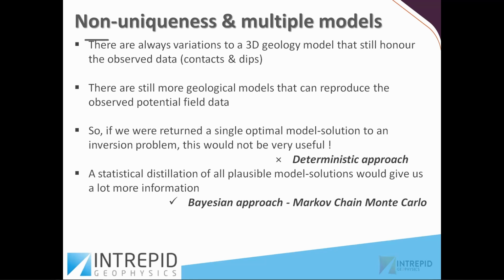So our job is to reduce the number of models that we are getting out of the inversion product. How can we do that? We can apply some additional geological information into the model to fix some of the layers, so that this layer should not change during the inversion. If we provide some additional information, we call it prior information or constrained information.